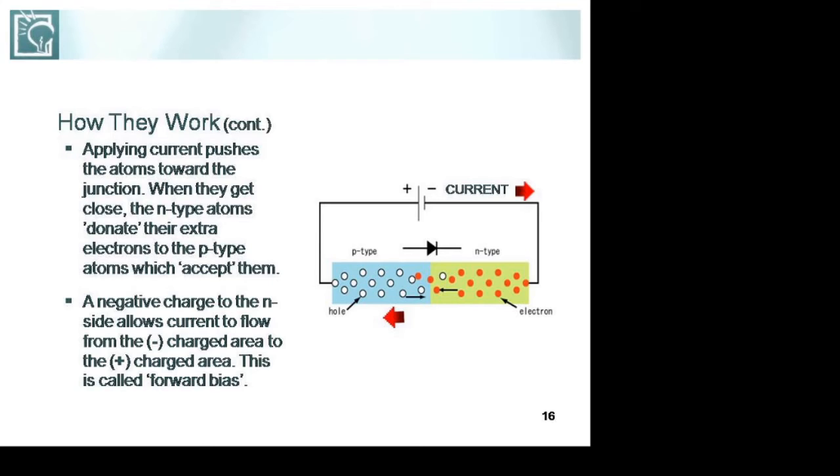The white dots represent the p-type charge carriers, and the red dots represent the n-type charge carriers. When I give a supply like a battery, with positive connected to the p-type and negative connected to the n-type, it is called forward biasing. When I switch on the battery, the electrons from the n-type will collide or mix with the holes. During this condition, light energy will be created.